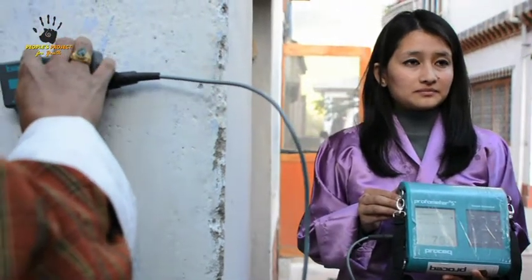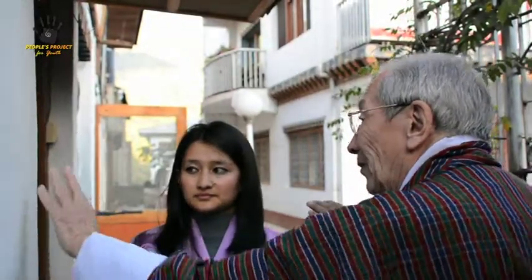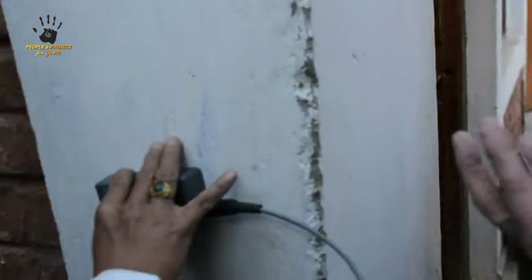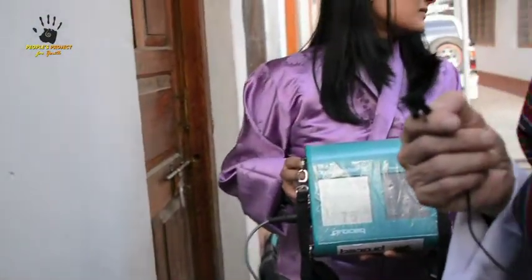2 bars in one face of the column. Right, so 2 here, so 1 there, and then further in, so 4 bars. So we've got 4 bars altogether here, which is a bit better than 2, isn't it? Yes. Because if there were only 2 bars in this pillar here, it wouldn't be very, very strong. But we're able to see all that without breaking up the column, just by magnetism going inside and detecting an iron bar.